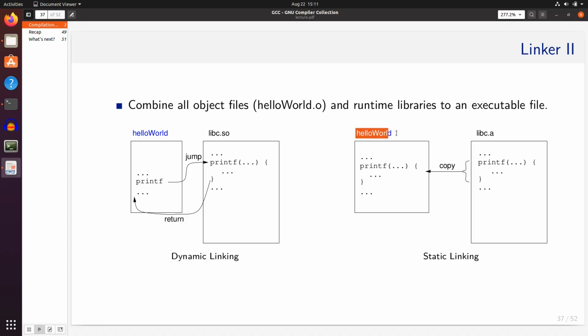The advantage of static linking of libraries is that the entire functionality is integrated into the executable, and this executable does not rely on any external libraries. Since we do not have a file system on the Atmega, we cannot have a file called libc.so and supply it along with our upload. Therefore, we need our I2C library to be compiled statically into our executable.